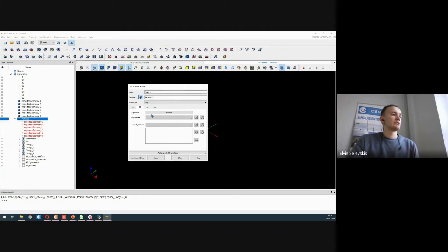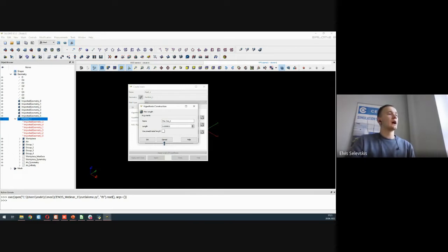And right now what we need to do is click here assign set of hypotheses, and through the automatic triangulation, which means pretty much through the automatic splitting into triangles. Then you will be presented with a max size value. What this means is it's asking for the maximum size of the triangles which should be made for this mesh one. So the size is the edges of the triangle.